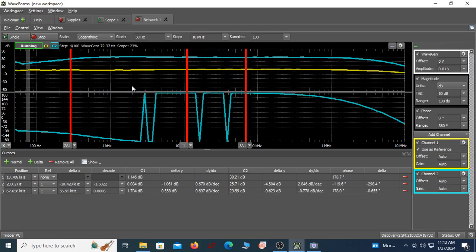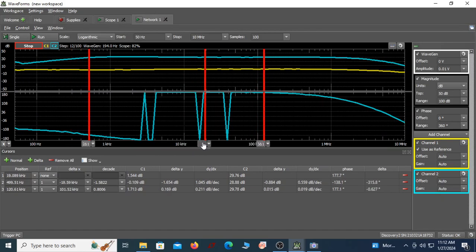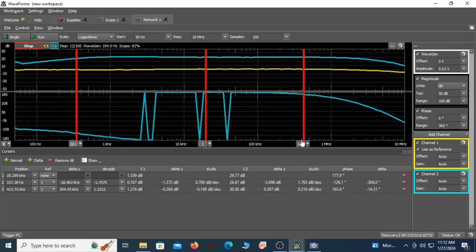Of course, you just follow the procedure properly. Whatever values come, that we'll see. Now this midband gain is around 30 dB, and then you keep this 3 dB down. You can see there's so much variation in the F1 frequency. It's almost there, 280, 330, not a major difference. But you see the other frequency has increased a lot. This bandwidth has increased a lot now.